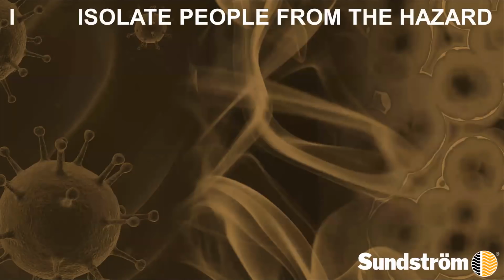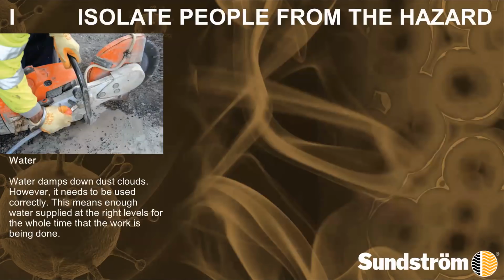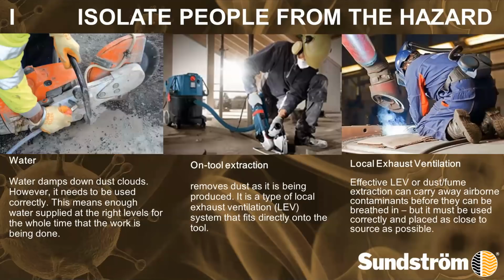We can isolate people from the hazard, and certainly in the construction industry, the 3 most common ways that we do that would be through water suppression. And you need to have enough water on here to make sure this is working. So not just a little dabble, the water needs to be on all the time. On-tool extraction, even in your local DIY stores, the tools are now available that will hook into your vacuum at home.